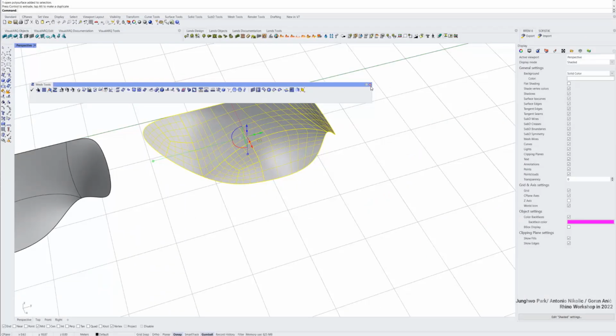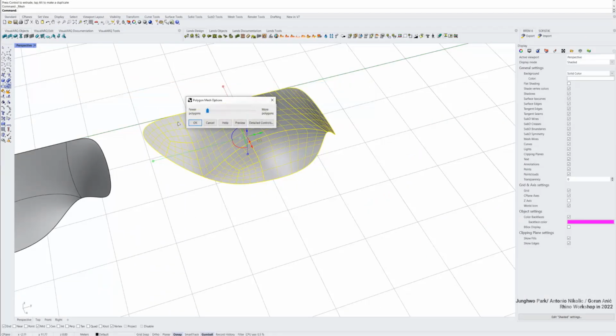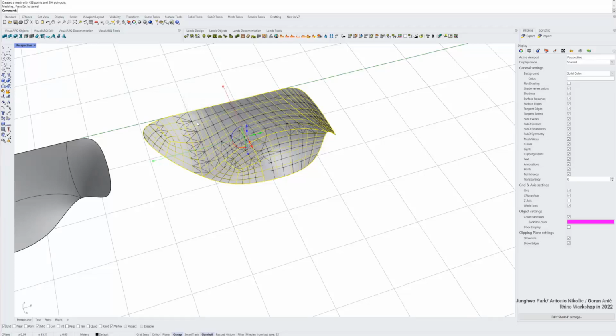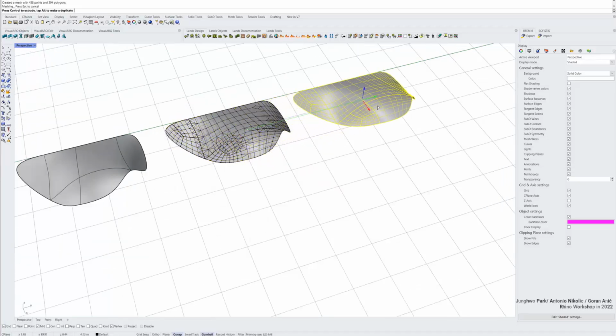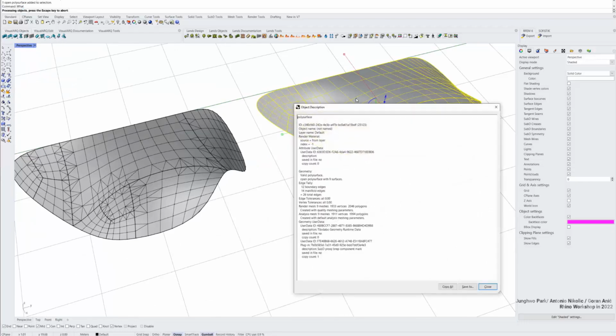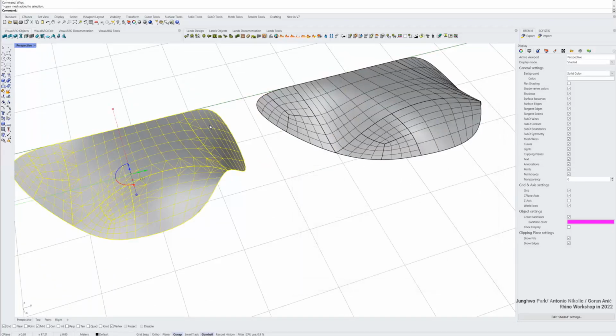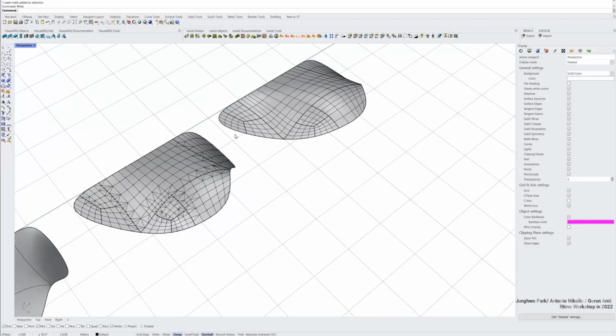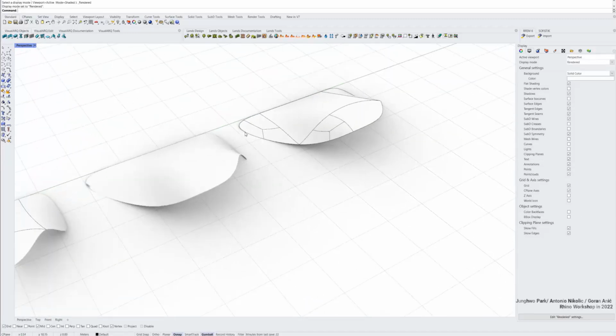So let's go ahead, and I'm going to click left, and I'll reduce the polygons, I mean, not many polygons. I'll make it minimum polygon numbers. When I change it, then this is NURBS. When you type what, this is poly surface, and when you type what, this is mesh. That's the difference.